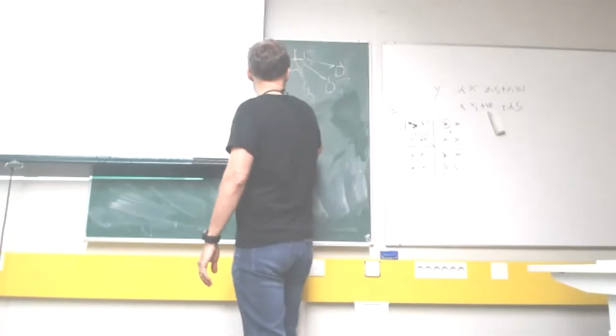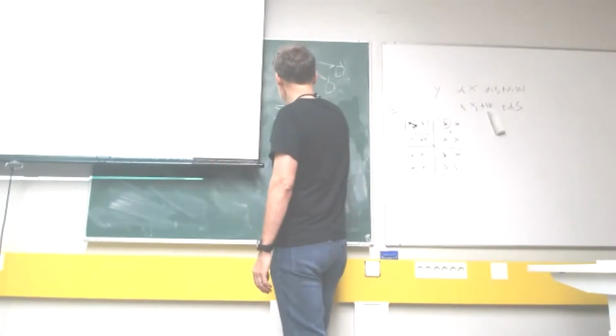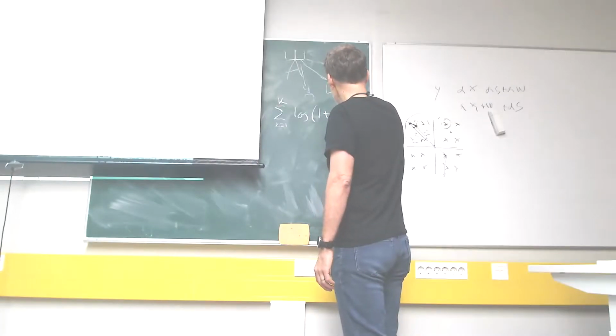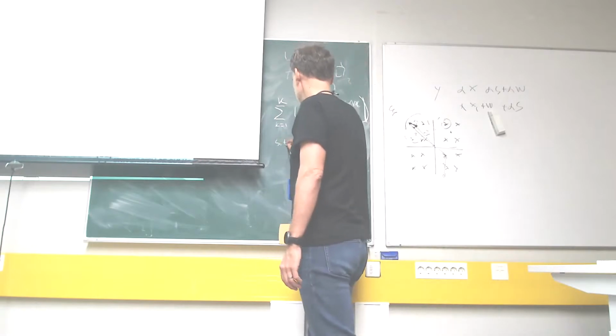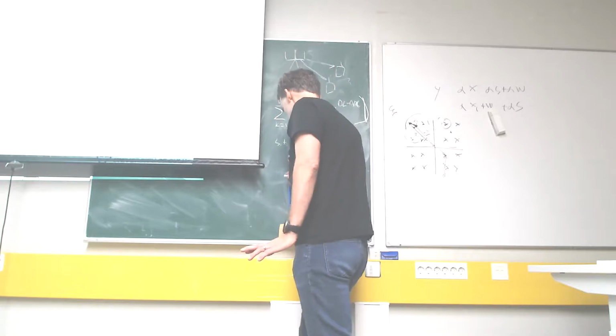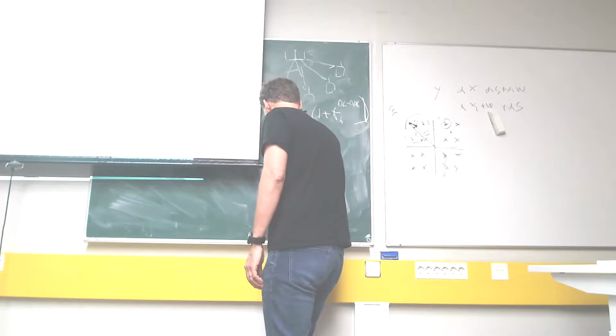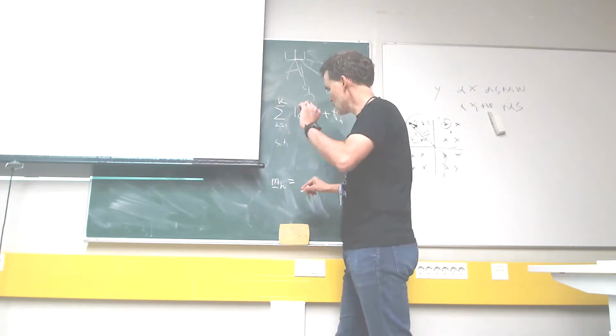So think about it. We have a problem to maximize the capacity of the downlink channel, the downlink DPC, subject to power constraints. Just to make things simple, let's define a new variable m_k, which is the downlink beamformer including the power.